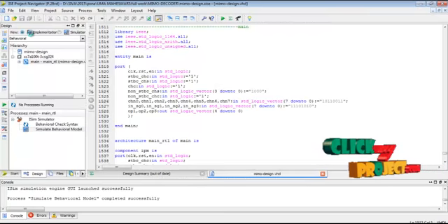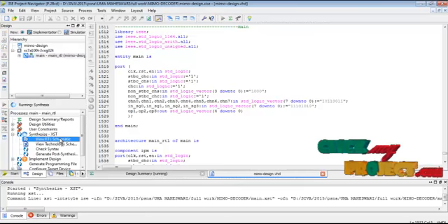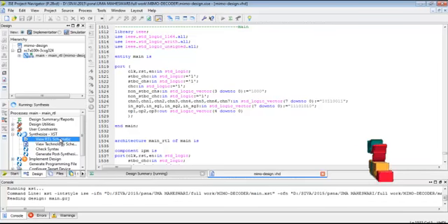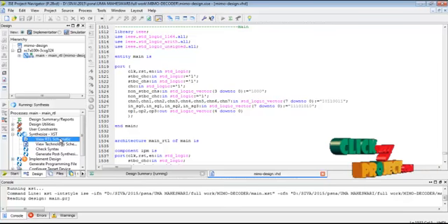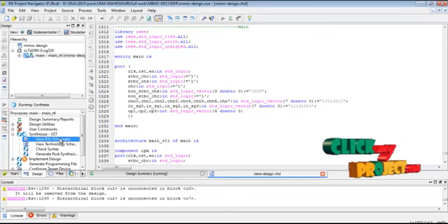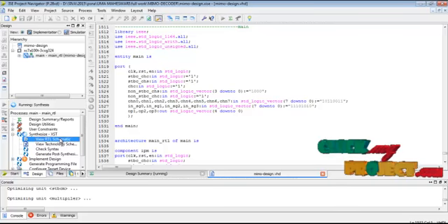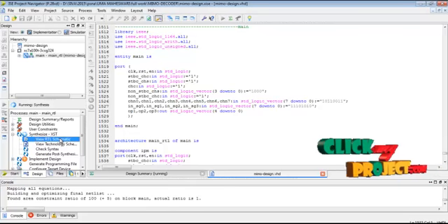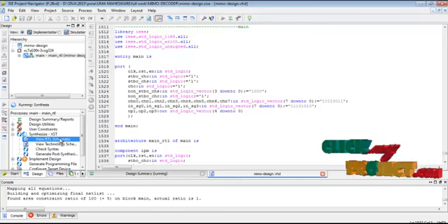Then we set the implementation work, and use it to view the RTL schematic for the overall architecture. This is the RTL diagram for the required logical structure at the register transfer level. This structure represents the logical blocks present in the overall MIMO detecting architecture. These blocks consist of the IBM and BCM, the LLR calculation, the Euclidean distance and the sorter unit present in the overall MIMO detecting architecture function.